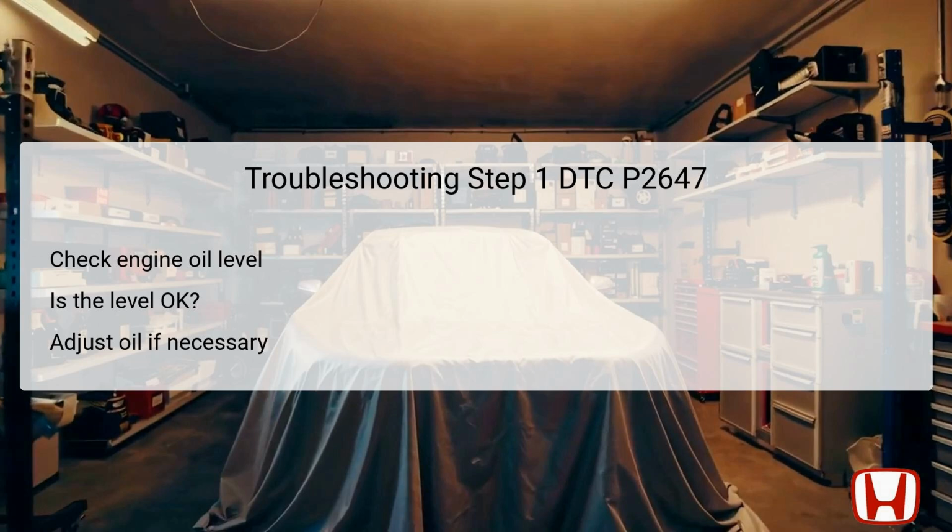If the oil level is found to be low, it must be adjusted to the proper level immediately to ensure that the engine is operating safely and effectively. This step is essential because low oil levels can create misleading diagnostic trouble codes, complicating troubleshooting efforts. Once confirmed that the oil level is satisfactory, the technician can proceed to the next step.